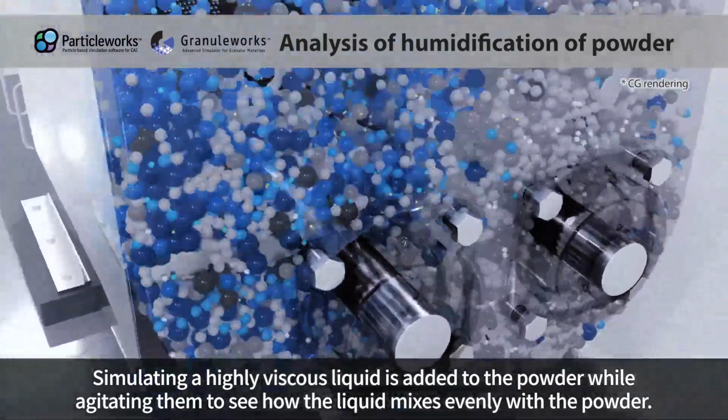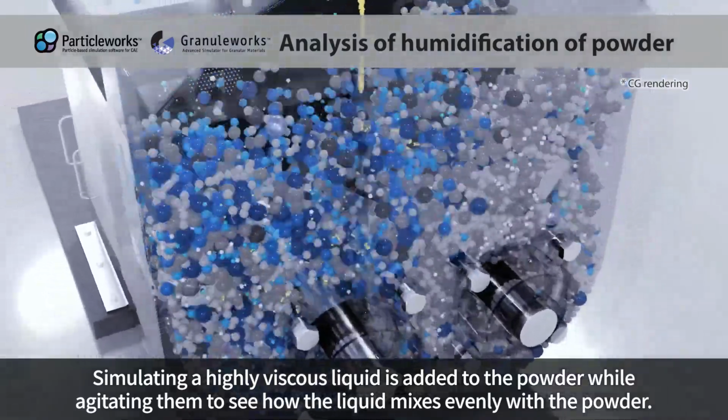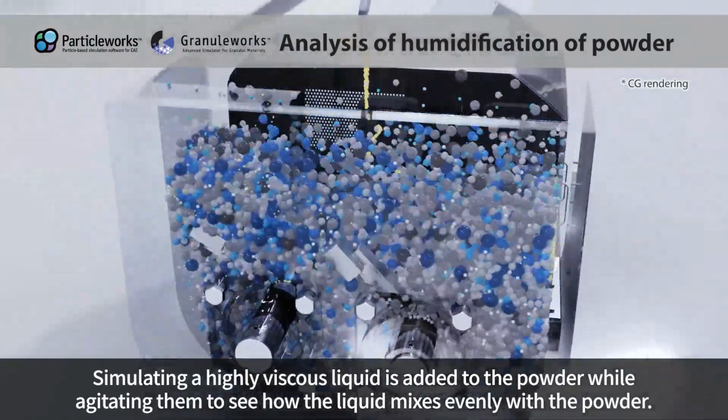It is difficult to disperse the liquid evenly in the powder and granules, and in this case, we can see how the liquid does not disperse sufficiently and adheres to the walls, and we recognize the need to improve the design and agitation conditions.